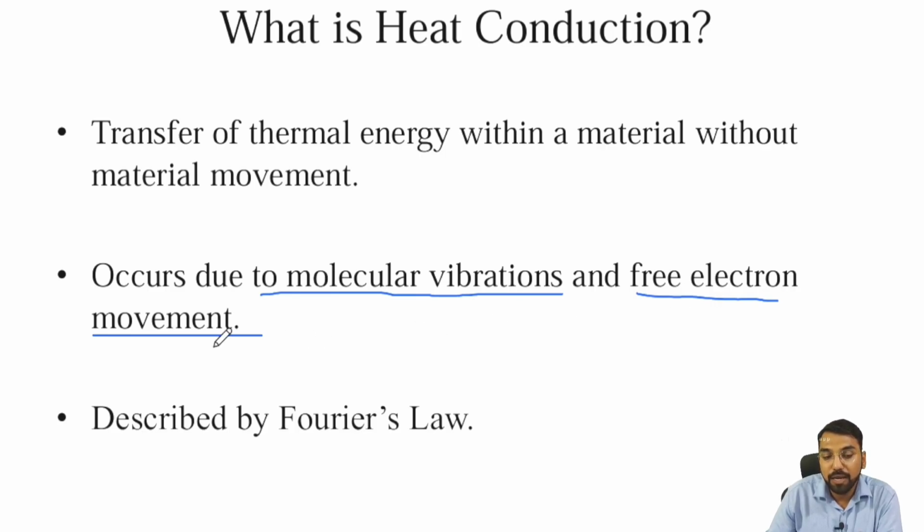Also, due to the free electron movements, heat transfer occurs, and that is nothing but conduction heat transfer. As in the last lecture, it is described by the Fourier law, where q is the heat flux, which is heat per unit area, equal to minus k dT by dx, where k is the thermal conductivity and dT by dx is the temperature gradient.